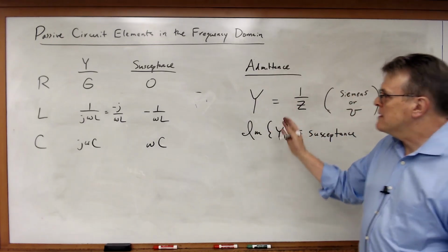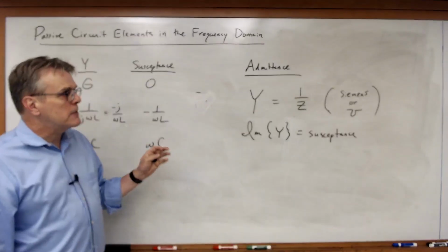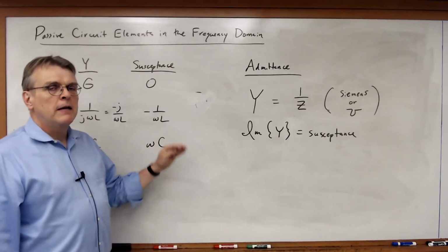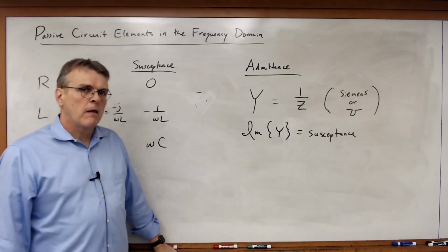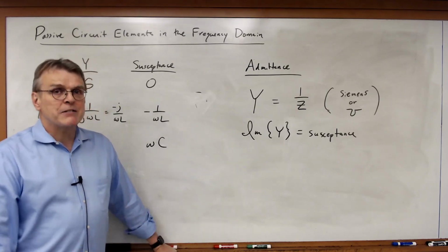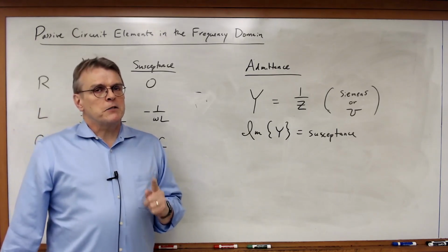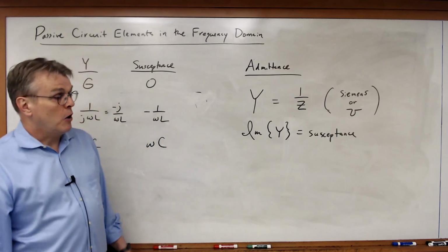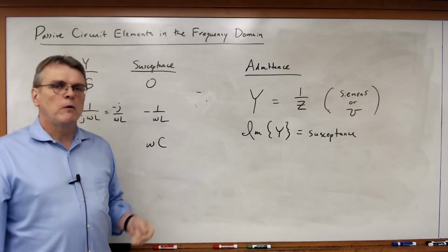And so here we have our definition for impedance, which now lets us transform any element into the frequency domain. So now we can transform sources. We can now transform passive elements. But if we're going to jump in and start doing circuit analysis, we need to know one more thing. Ohm's law works. Do Kirchhoff's laws also work? Well, we'll look at that next time.